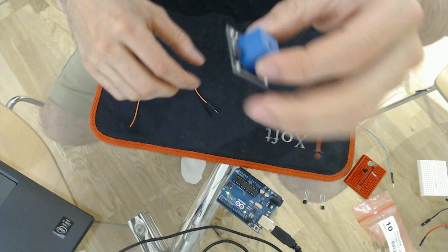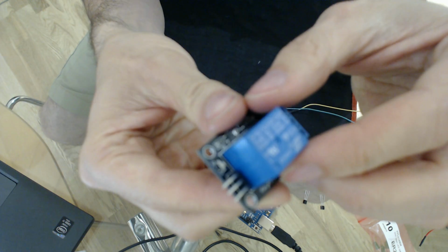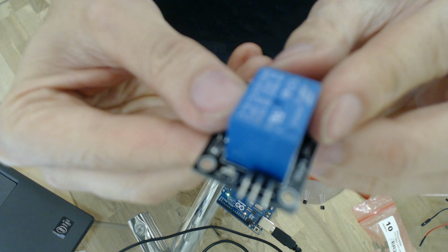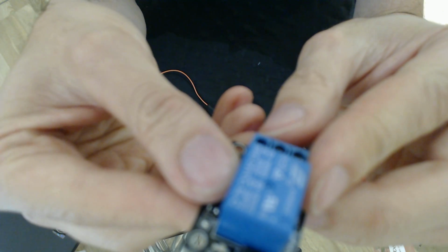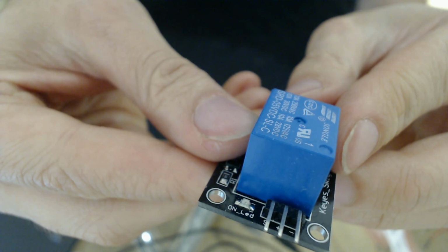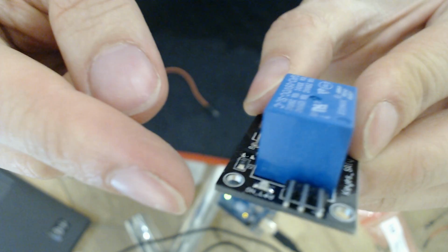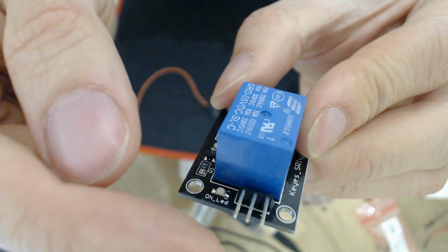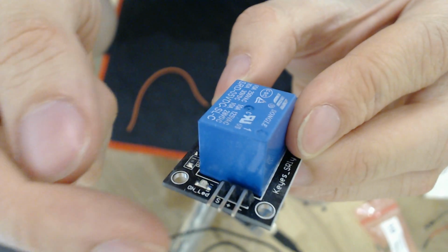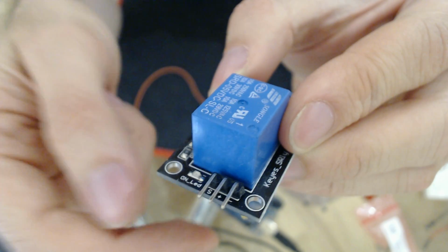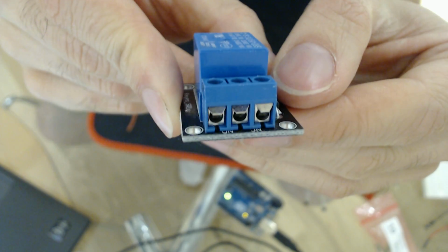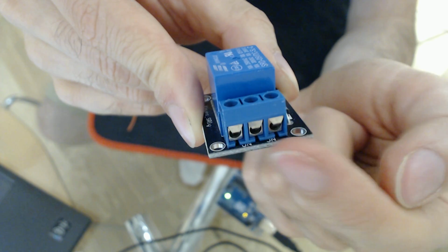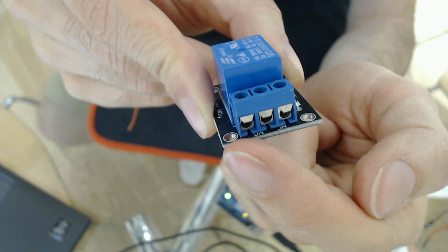So let's see if I can show you the pins here. If it gets focus. Right. So you can see a small label down there. This is a signal. And the middle one is 5 volts and the last one is ground. On the other side we got these ones, where the middle one is the common, and on each side is very short, like neutral, like no state, and when you send high it shorts this one.